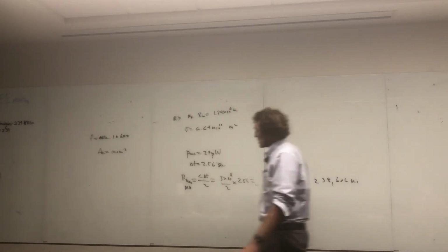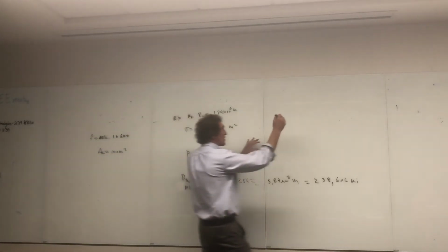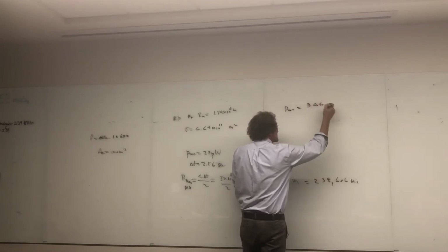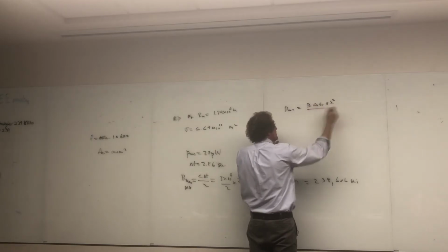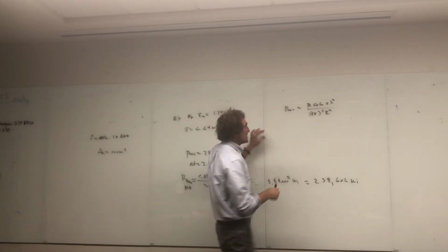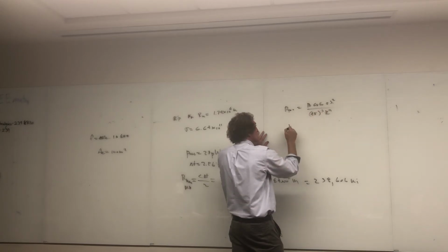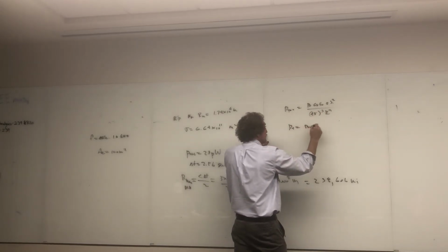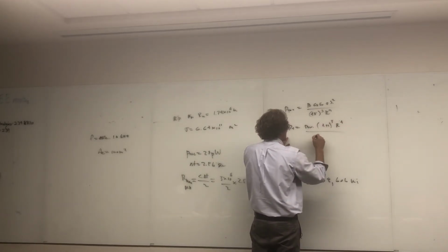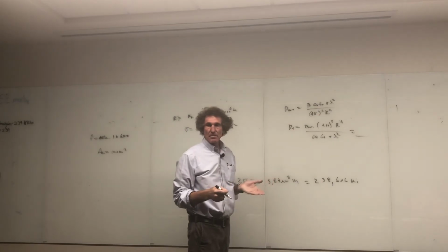If we want P radiated, I'm going to go backwards fairly quick. So P received, we know, is equal to P transmitted, gain transmitter, gain receiver, times sigma times lambda squared, over 4 pi cubed, R to the fourth, right? You don't have to do this, but just watch. If we want transmitted power, the only thing we do is multiply by 1 over everything else. Transmitted power is P received, 4 pi cubed, R to the fourth, distance to the moon, over gain transmitter, gain receiver, sigma lambda squared. And that's it. You're doing a simple inverse problem.